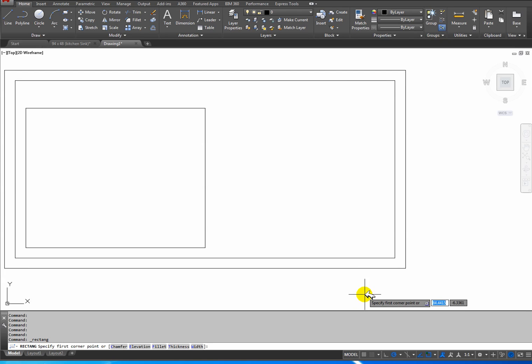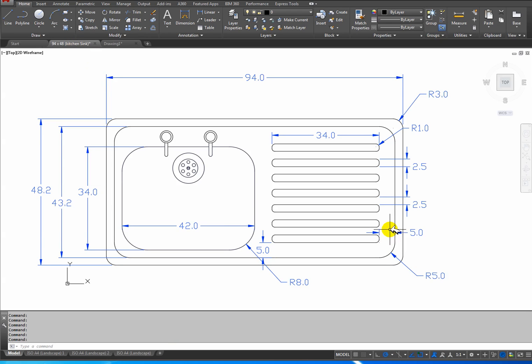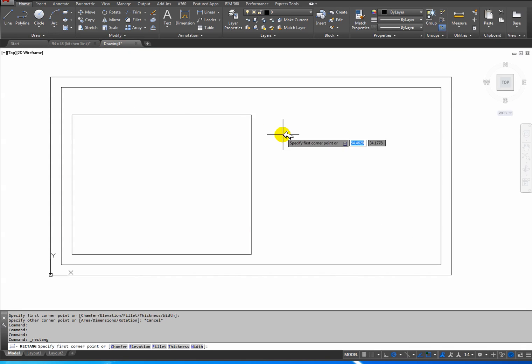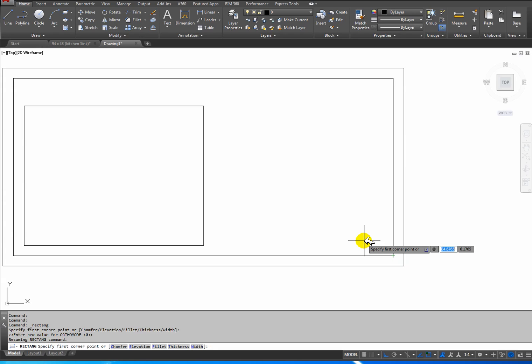So what I'm going to do is, remember how I created this rectangle, I'm going to use a very similar method. So for x in this case will be 5 and y 5 actually. That's easy, makes my life a lot easier. So I'm going to say show that point. This time I'm going to type again the word at. X is going to be minus 5 because we are coming minus this way, comma, but for y I'll type just 5.